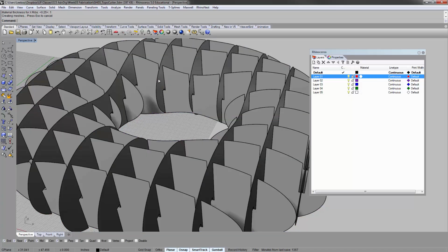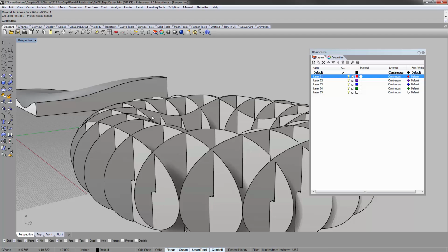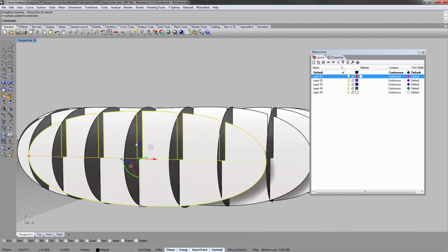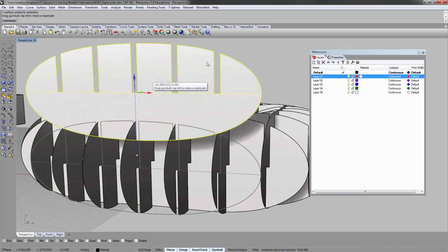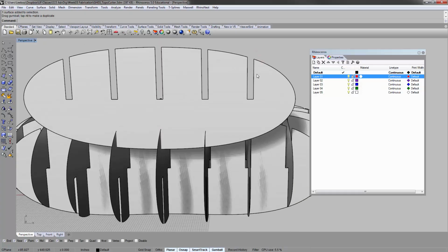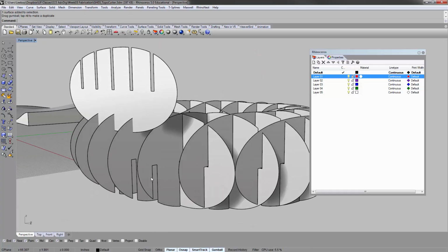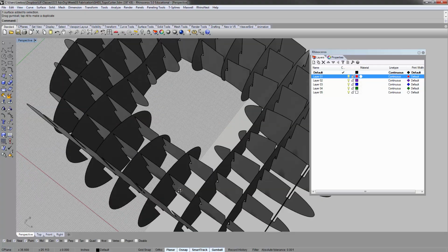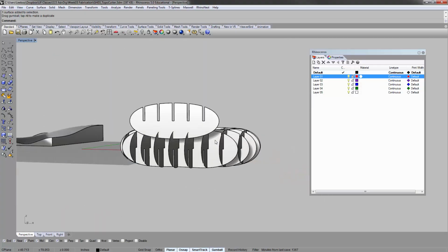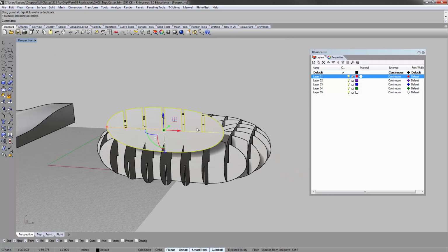And it'll pause for a little while, let it run, and there you go. You'll see that this has automatically notched in the right location with the right width and thickness to fit everything together. Essentially the X ribs are notched so the Y ribs fit downwards on top of them.